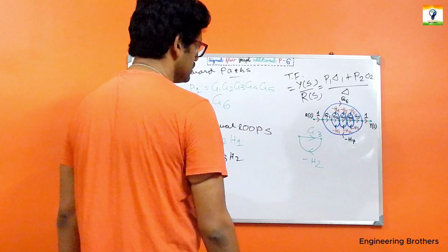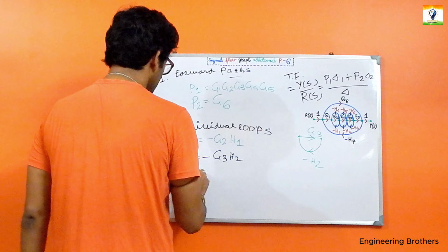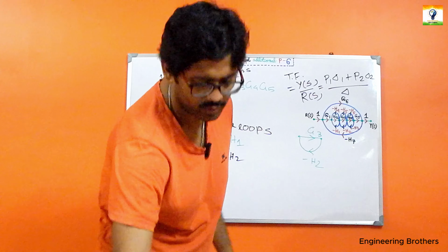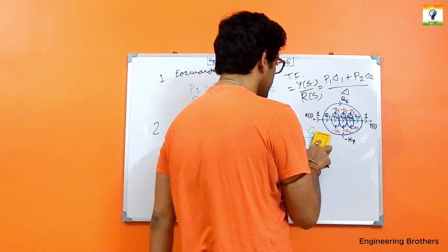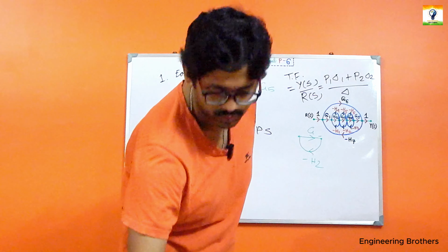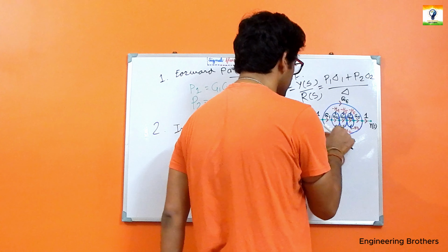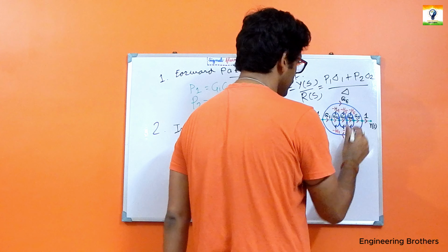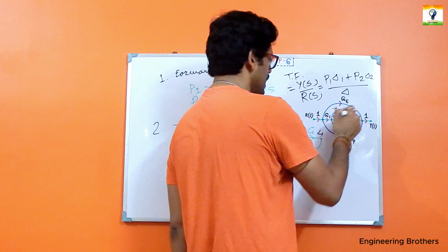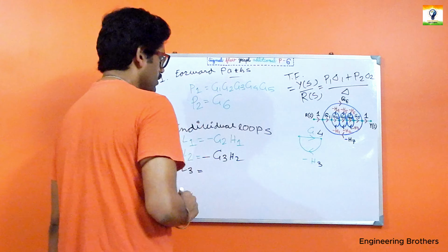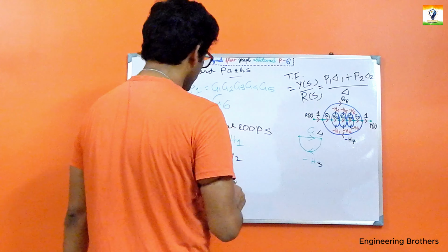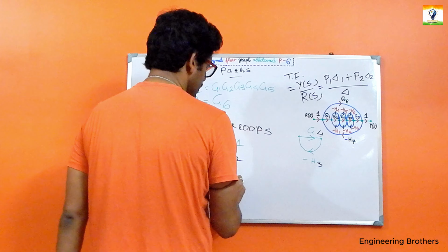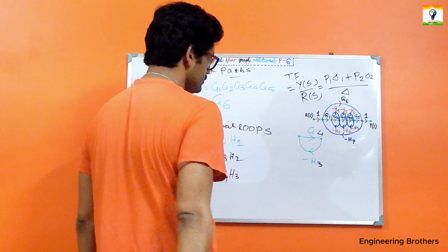Similarly, for our next part we have got the individual loop L3 over there, and for that one we once again change the gain for the considered part, which is quite naturally our G4, and this one will be interchanged as our minus of H3. You can clearly see according to our diagram. Now for that considered part, the loop for that one should be minus of G4 H3.